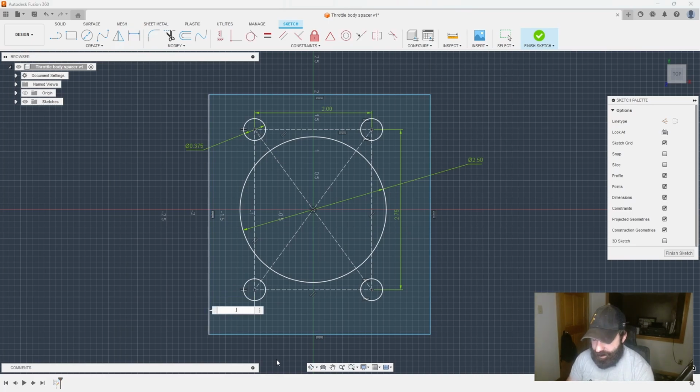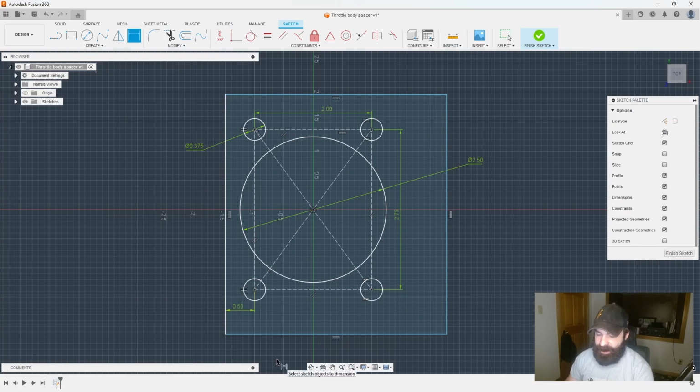And with that, I'm going to set it to a 1/2 inch on both sides. So again, I'm going to go to one side and then back to the other. Since I want both these sides the same, one neat thing I could do is click this first dimension, and you'll see that D5 appear. What that D5 is telling the software is this dimension is the dimension I want here. So I'm going to go ahead and hit enter.